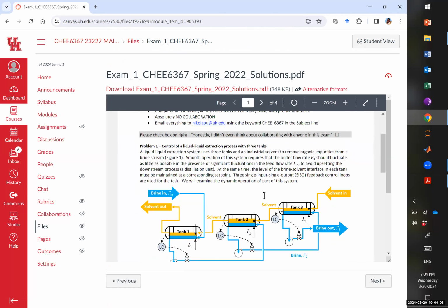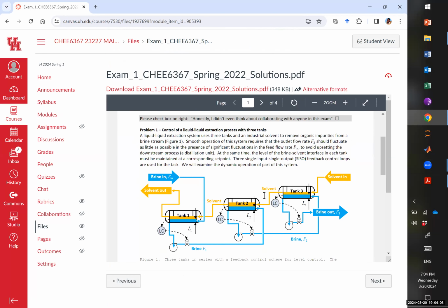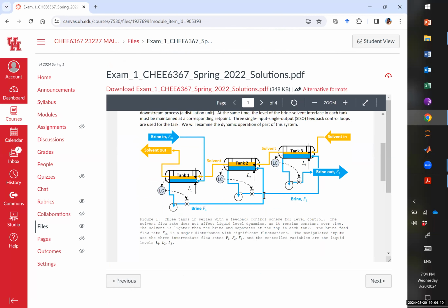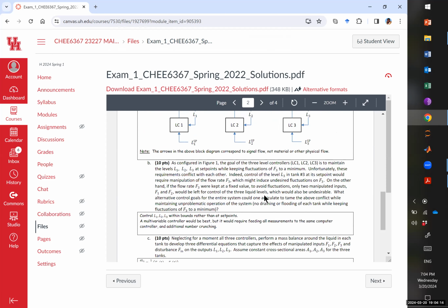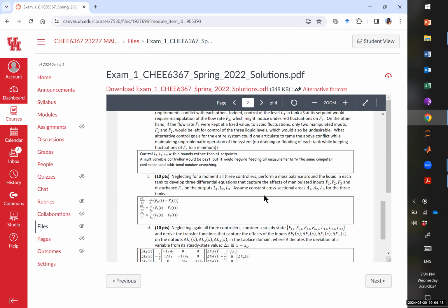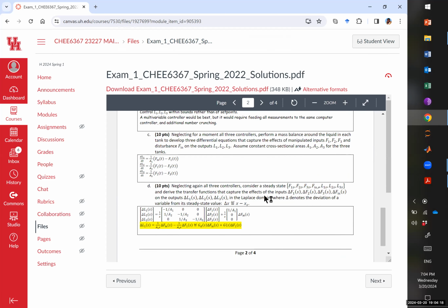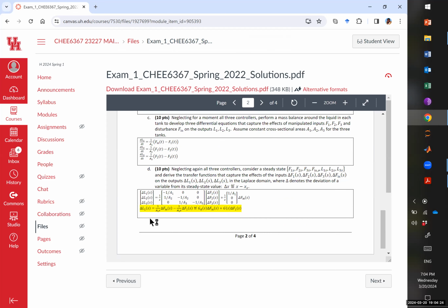So was it this one? Yeah, so you're tuning the controller for tank 1, and your transfer function is really simple. It's just 1 over S times A, which is an integrating transfer function, right? So if you try to use Ziegler-Nichols in open loop, it's just going to go to infinity because you just increase the flow rate without. Yeah. So I was just asking, what is the appropriate way to tune something like this?